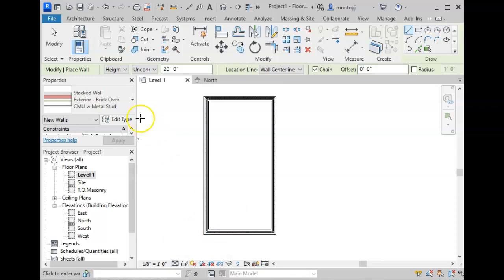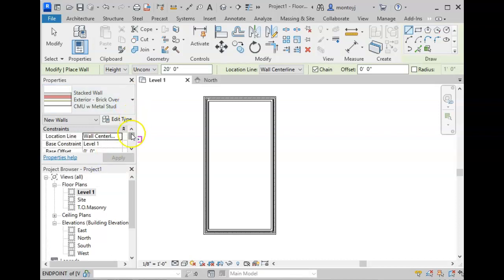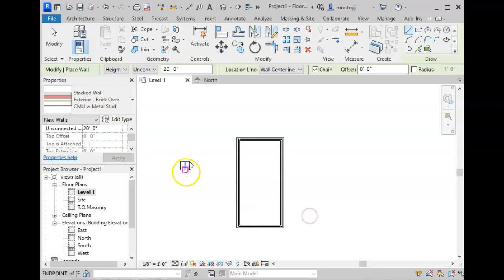Okay, and we can also check the height. I'm working on a smaller screen, so if I did want to check the height, though, you could see that here's the unconnected height of the wall is 20 feet. And you can open this up to take a better look at it. These are elevation tags. Here, you get one for each corner. Be careful not to erase them. They're hard to retrieve. And I could have drawn this with a rectangle had I chosen to do so.